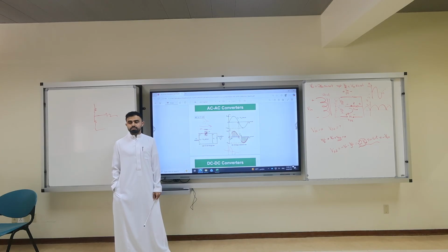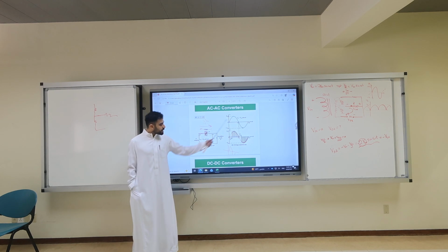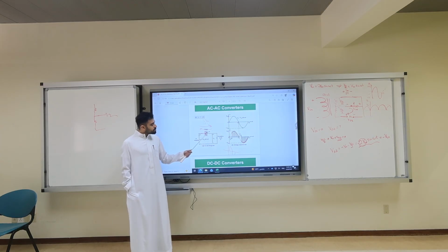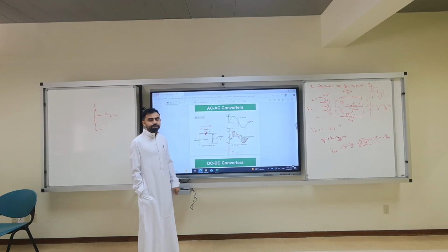But to get the wave in this shape, do we need continuous pulses? I think it's just one pulse. No, only one pulse. Positive, negative, positive, negative in a sequence? No. During a negative cycle, if the anode is higher than the cathode, it will conduct. If there is no pulse to turn it on, it will be zero. It will be like there is no output.